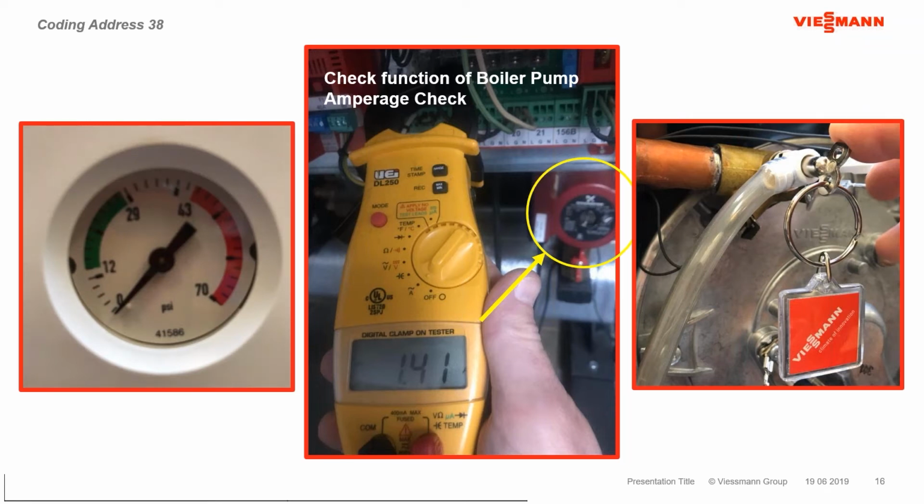So basically, is the pressure down in your boiler? Get that pressure back up. If there's no pressure, the pump can't basically push that flow switch closed, and you're going to have some issues. So there's some problem with flow with a value of 2 at address 38. And if the flow switch is not the issue, then we're looking at some sort of problem with movement of that fluid through the boiler, whether it's a pump issue or air or pressure or some isolation valve closed or some combination of those particular problems.